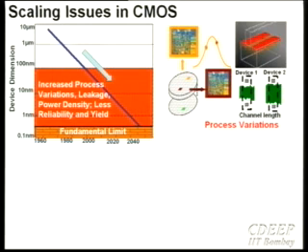As I mentioned last time also, if you look at dies coming out of different wafer lots, there's a good amount of variation between the transistors, from one wafer lot to another, from one die to another. On top of that, there is also a random variation, and that could be due to random dopant fluctuations or line edge roughness and so on. If these variations are really large, then in order to have high yield, you need to go to the worst case corners of your design.